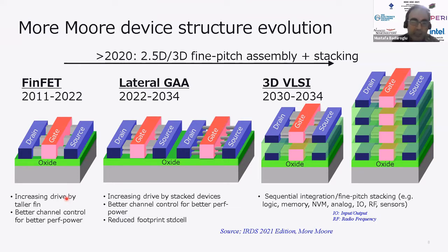And then you have heard about the announcements of the lateral gate-all-around device picking up. We call this nanosheet. And that's providing much better performance than FinFET because of better footprint per drive. So this is allowing us to get more performance per unit area from this cell. And also better low power and DTCO enhancement, because you can choose the width of the device depending on the design rule, reducing the size of your standard cell area by carefully selecting the width of the devices in your SoC.